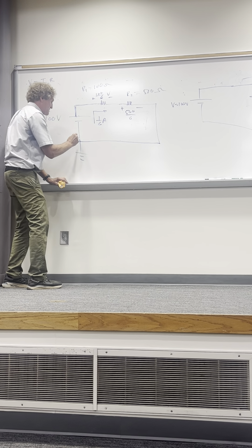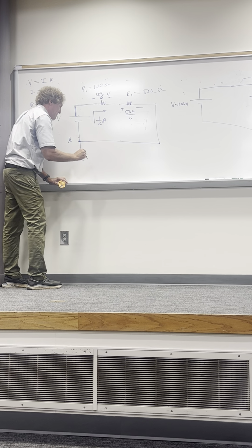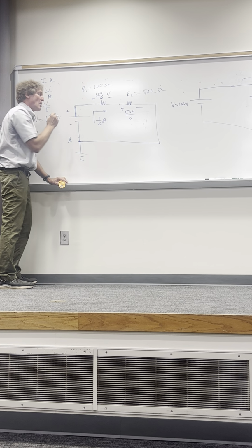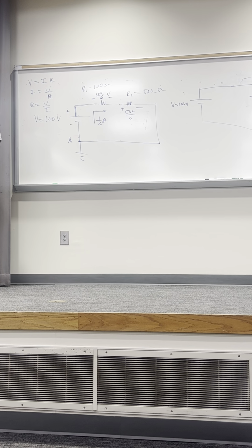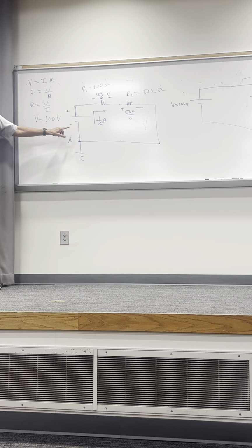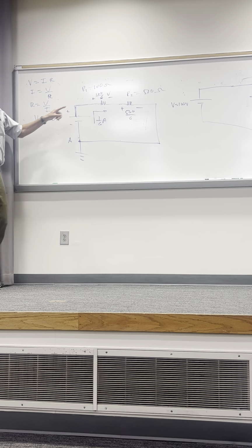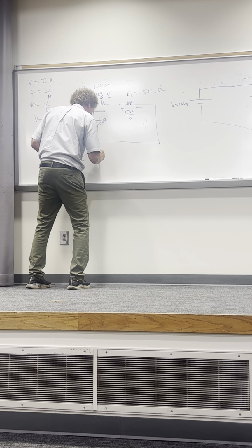I'm going to start at this point. You always start at a point. Call it A. So I come, and notice I hit a negative to a positive sign of voltage. This is important. Now, pay attention. Y'all hear me? Anytime you go from a negative to a positive as you're summing voltages, that is a voltage increase that's considered positive. Y'all hear that? So it's going to be plus 100.